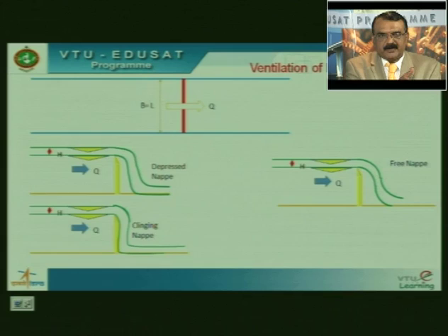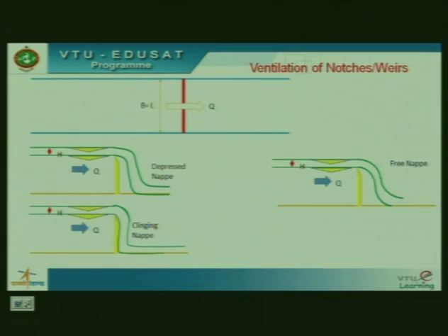Up to this sill level, there is no discharge. This is one bank, this is another bank. You have one wall here and another wall, and in between these walls you put this notch. Now, water starts coming from the upstream side. Up to this acts as an obstruction. Up to this sill level or crest level, there is no discharge. Come to the downstream side.